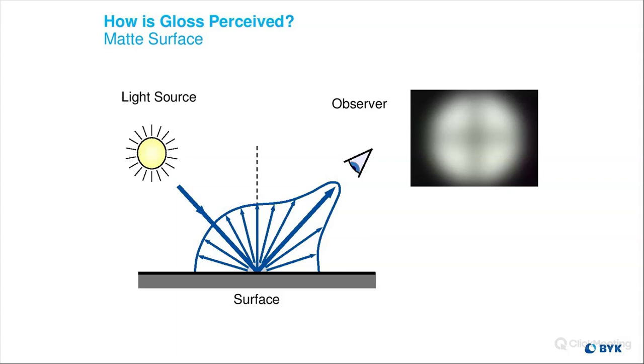You can get dullness in the paint. It may not dry, or may take longer to dry, so you are going to get different sheens. You're not going to get the same finish overall. So temperature and humidity will play a role in your gloss values.